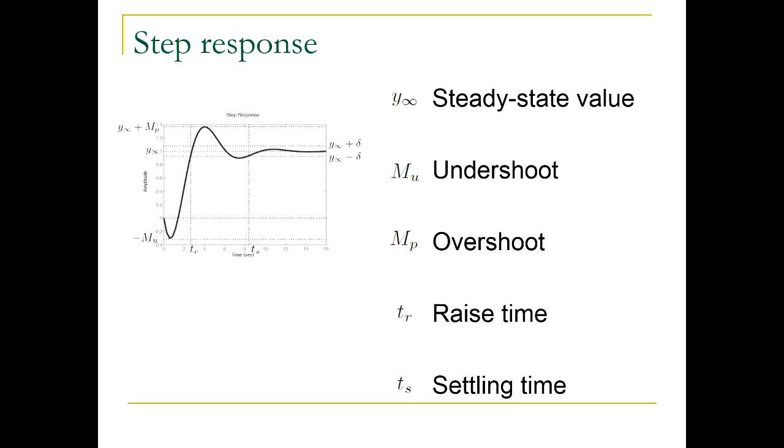And then you can also talk about settling time. This T_s is the settling time. This is the time needed for the response to get to within some margin of the steady state value. So maybe you can ask, how long does it take for my response to be within 1% of the steady state value, and then stay there forever? That's the settling time, T_s.